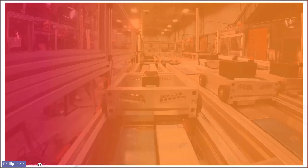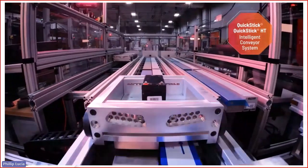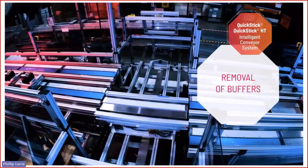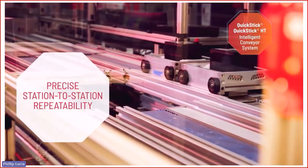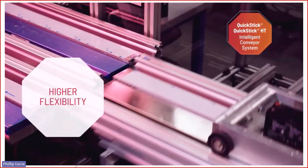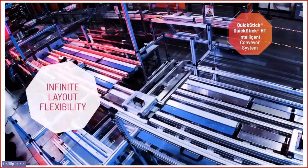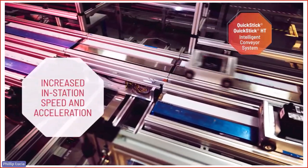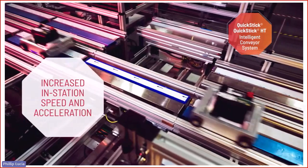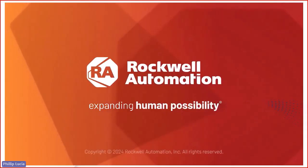Next is a video showing a switch track application in the automotive industry using the QuickStick system. This can help remove non-productive buffers by efficiently routing product with high precision, repeatability, and flexibility in layouts. You can dynamically group similar products at stations to level load production and enjoy the freedom of infinite layout flexibility and increased speed and acceleration through defined safe zones. QuickStick is similar in concept to MagnaMover, but it is capable of larger payloads and offers more customization in terms of movers and their support structures for customers to choose components that work with their system.